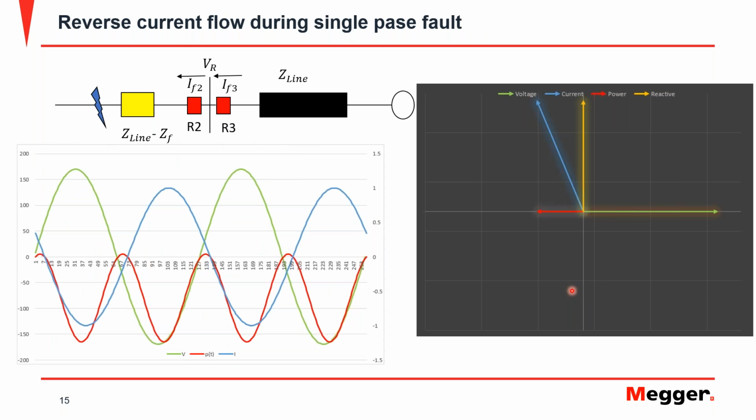voltage. If the fault happens behind the relay, and here we are showing the waveform as seen by R3, this relay that we have here, if you guys remember from the first few slides, do you remember that for this relay there, the current was inverted from the normal flow, because now that we have the fault here, this relay was supposed to be looking in this direction.